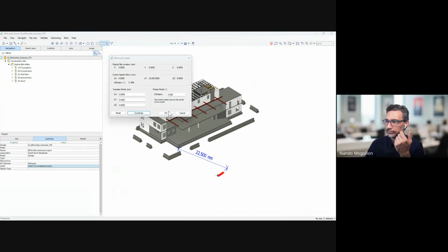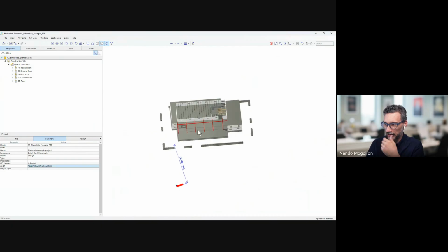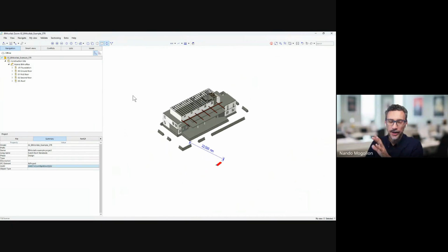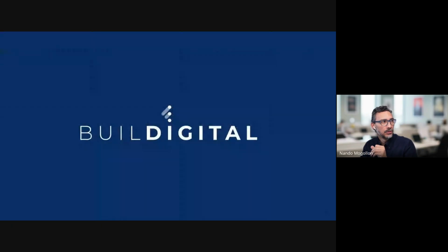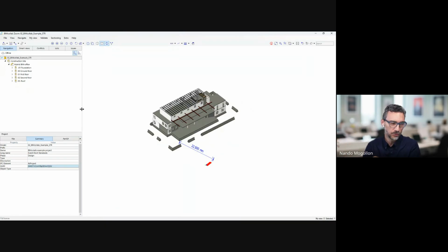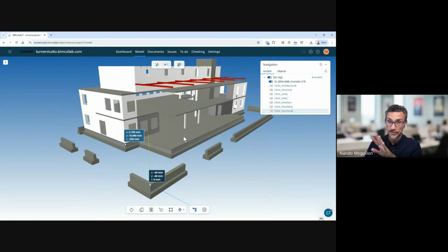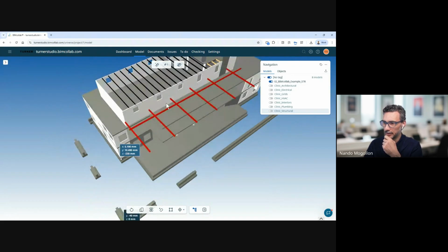Again, it's not going to do anything because I'm going to show you what it tells me. It says the model is already coordinated. I don't have any other model to coordinate against, so it's just going to tell me that. And the location is going to be whatever location I have currently. All right, so that's for double checking locations using BIMCollab Zoom and flipping back to Nexus, checking it on the online viewer simply by, remember, this is a manual upload. This is not going to follow whatever locations I put in there on the other one. I have to do something else